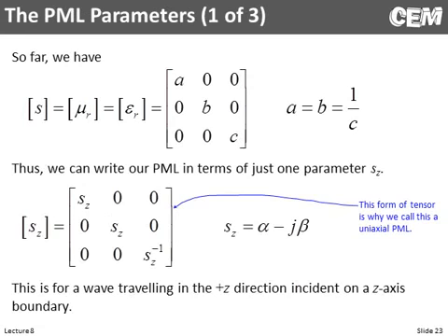We made the material diagonally, oh man, sorry, just went to the next slide. We made our materials diagonally anisotropic. We made square root of B times C equal to 1, and we made A equal to B. Okay, so now let's look a bit at what we need to do with A, B, and C. So here we are. Here's our tensor, and we could summarize those two conditions into one equation. A equals B equals 1 over C.